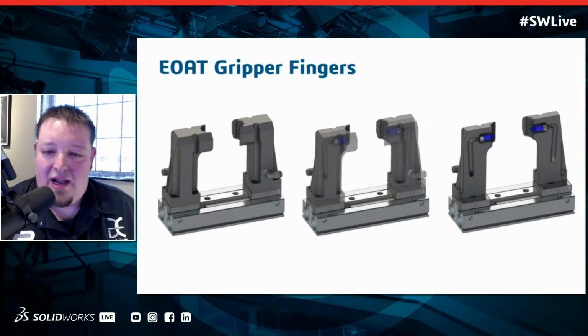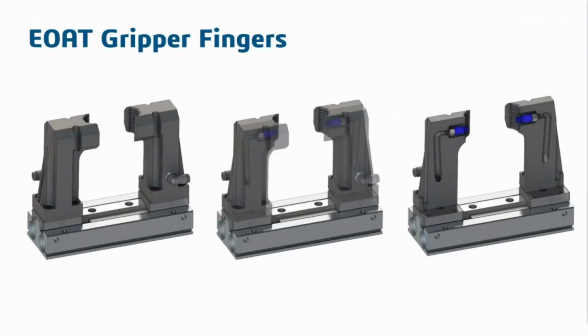So looking at this slide right here, you can actually see a cutaway in SolidWorks. These gripper fingers are printed out of nylon 12. And the beautiful thing about MJF is these parts are airtight and vacuum tight coming directly off the printer. So unlike SLS or FDM, where you're going to have to do some kind of sealing process with something like super glue, essentially, here they're 100% dense right off the machine, no leaks.